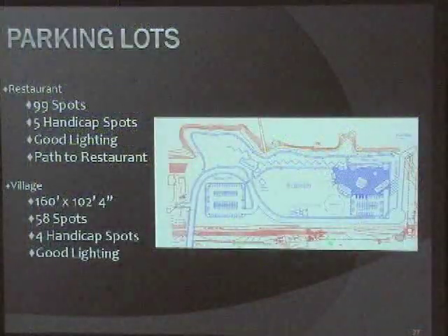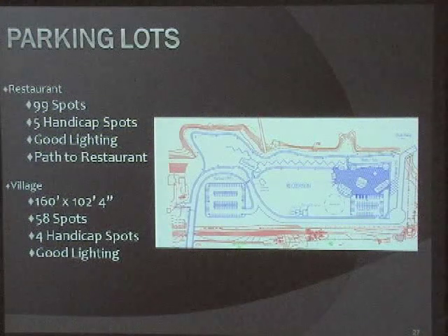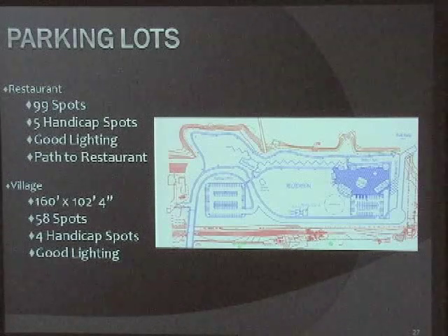Hi, my name is Mike. I was also part of the structural team, but today I'll be talking about the parking lots. We have the 2 parking lots. This one's for the restaurant. Both parking lots are designed to Tiverton municipal codes and ADA standards. With the Tiverton municipal codes, you need 1 parking space for every 4 patrons at the restaurant. And then we also put 1 in for every employee.